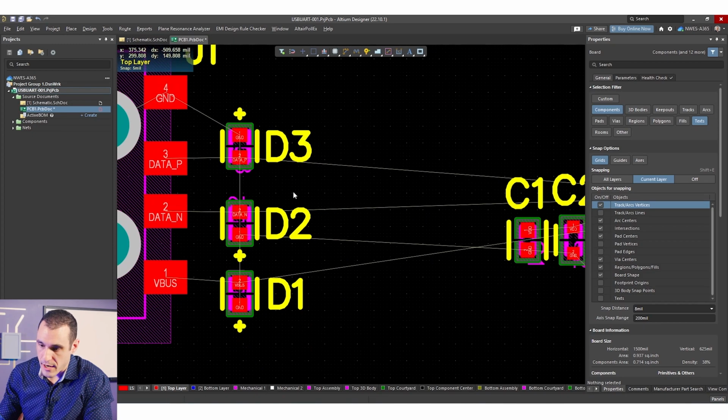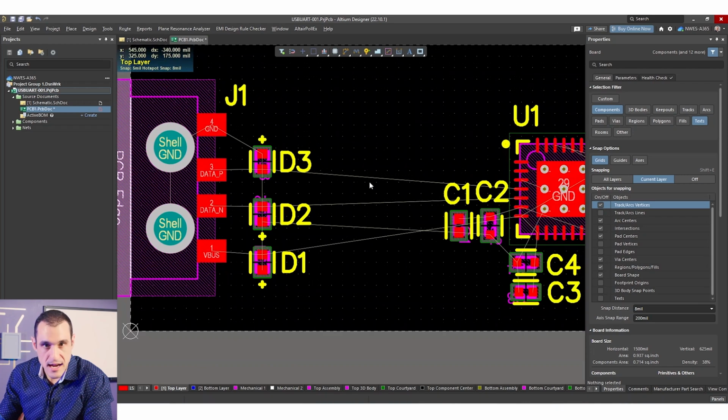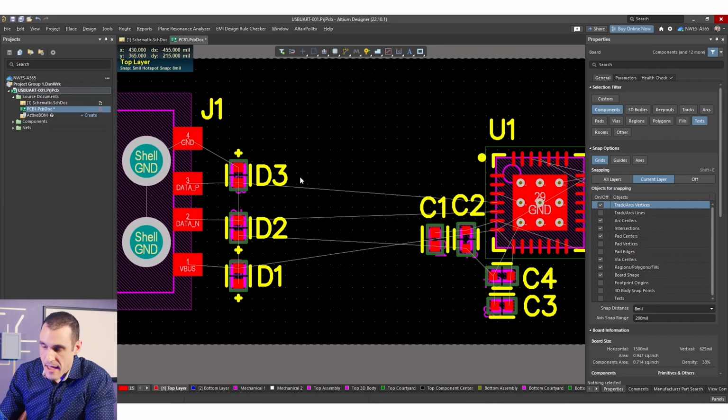These being differential pairs, even though this is a short distance, I think it is important to, of course, route them as you would differential pairs, and that means you need to design them to the correct impedance. Because this is a 2-layer board, you have to take the strategy that I talked about in our USB on a 2-layer board video, which is to do this in a coplanar arrangement.